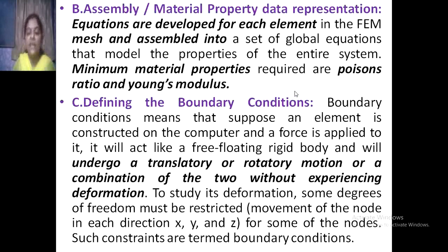So to study its deformation, some degrees of freedom must be restricted. That means movement of the node in each direction, x, y and z, for some of the nodes.